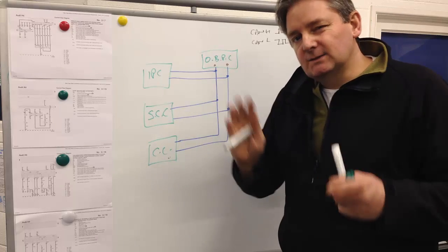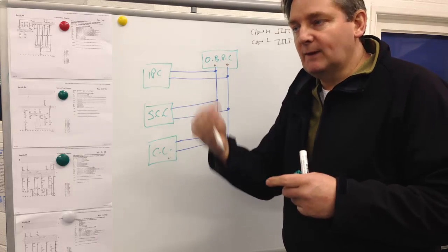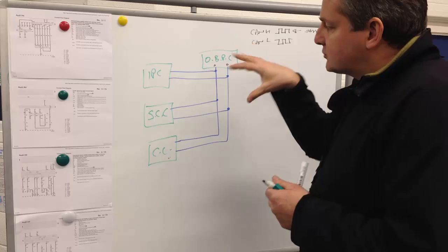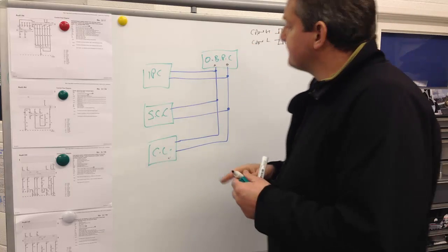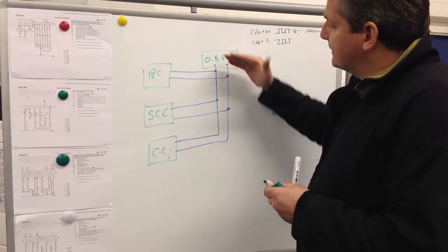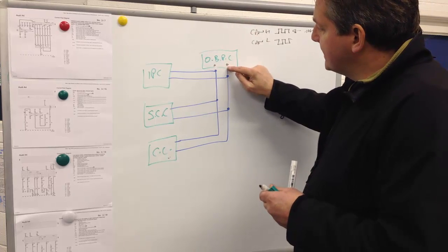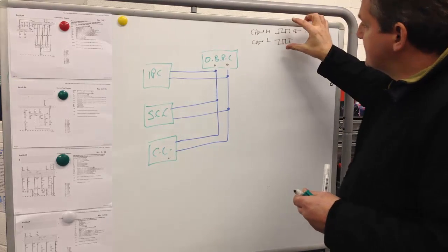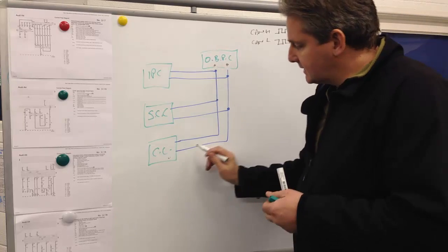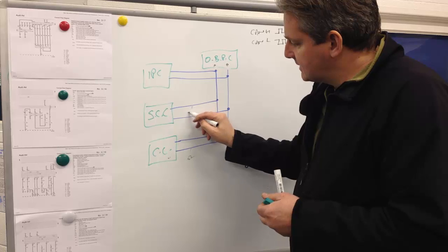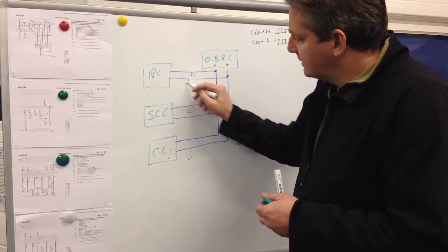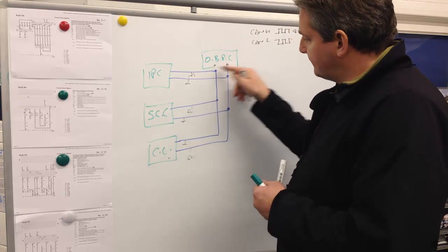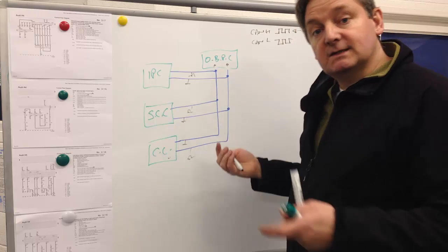What we're trying to work out now is actually why the symptom is present with the waveform, and we're just taking a look at the layout of the circuit diagram to see if there's any way, or to try and work out what our conclusion could be about a diagnosis. The interesting fact is, if with this disconnected, so we have no connection near A and B, and we measure the waveforms across here, we get perfect CAN high and CAN low. Now, this is our first clue. If in our circuit somewhere we had a problem with resistance or a short in any one of these lines, we would expect these faults that were affecting this network to be present with it disconnected.